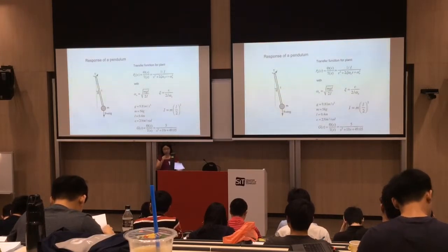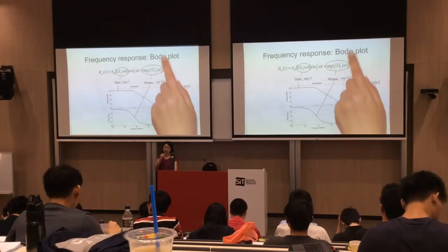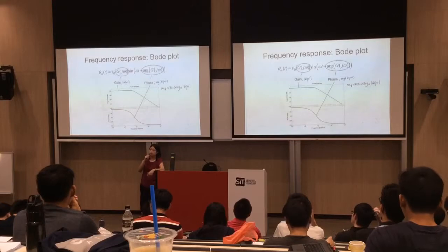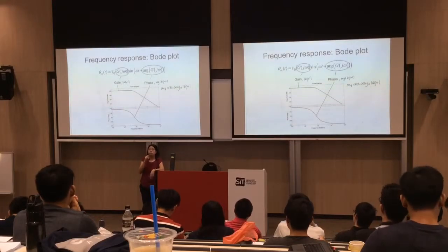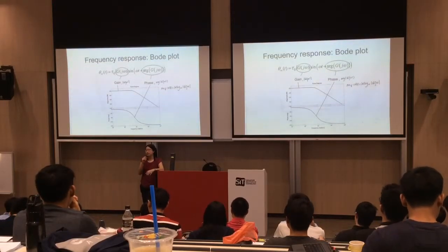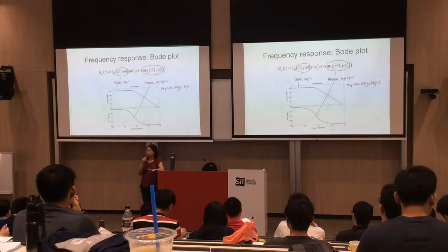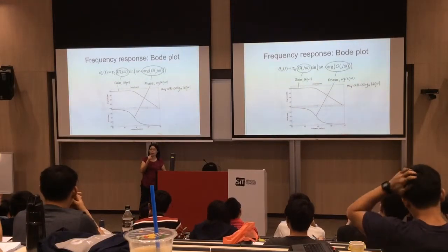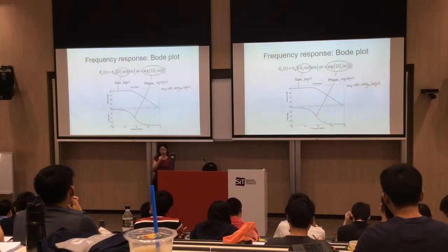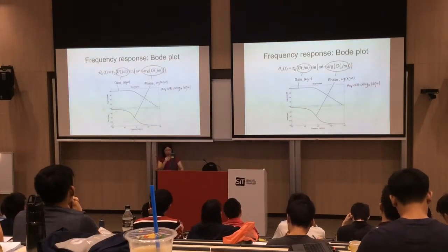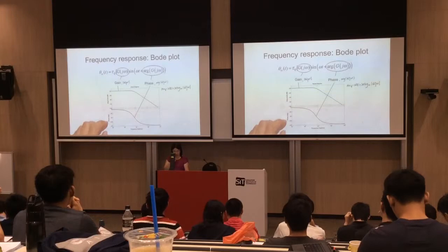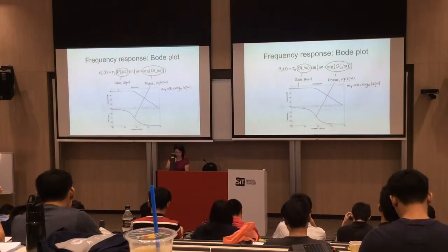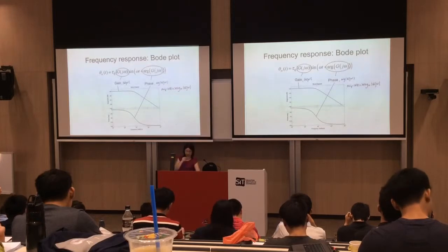So we are going to plot the Bode plot because there are different ways of pronouncing this. If you go into Google, some people say Bode, there's also Bode, but definitely you don't pronounce it as Bode. There are many ways of pronouncing this. One of the ways is to call this a Bode plot. So what do you draw for Bode? You draw the gain and the phase. Gain specifically, you often convert it to dB, and the phase in degrees.